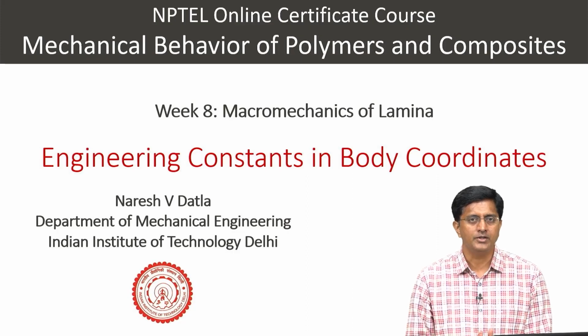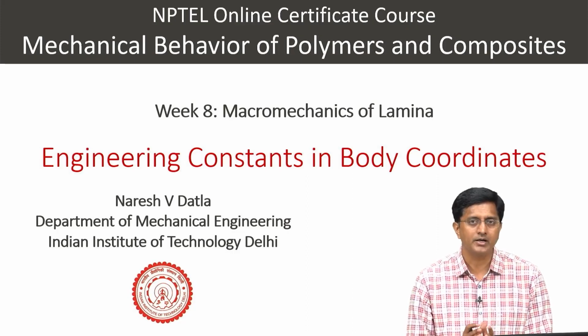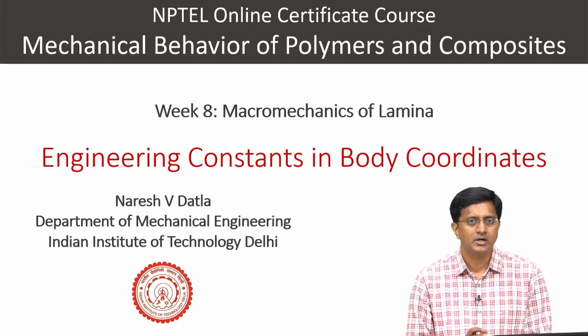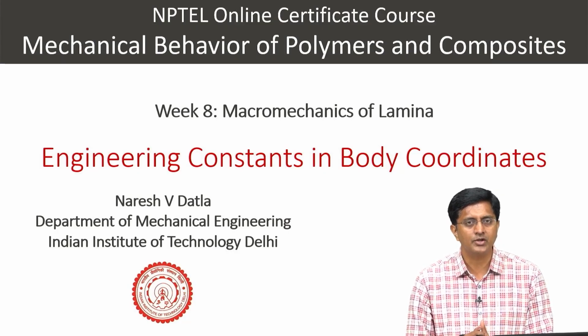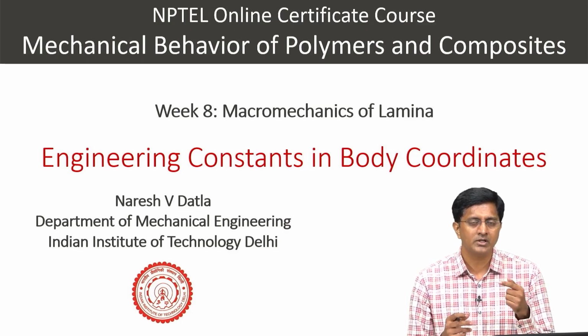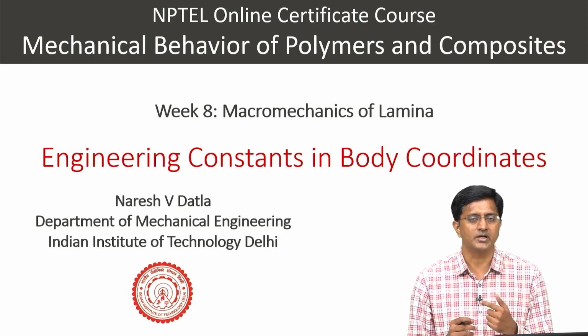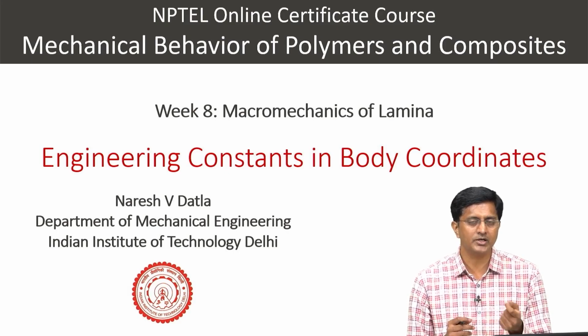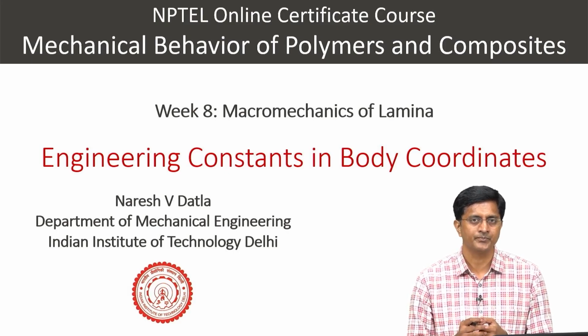Hello all. In this video we will be looking at engineering constants. Until now we have been looking at engineering constants such as E1, E2, G12 and Poisson ratio nu12. But whenever we talk about these constants, these are in the material coordinates, which means when I say E1, the direction 1 is the principal direction, and similarly E2, the direction 2 is the principal direction.